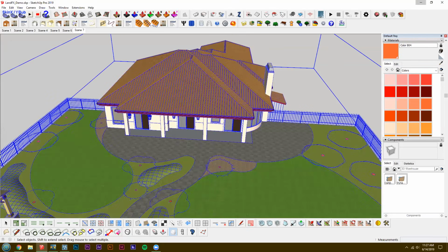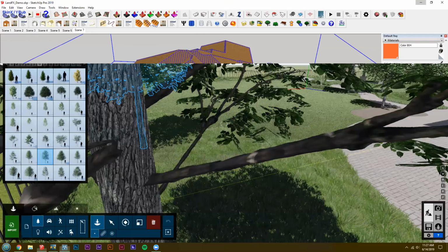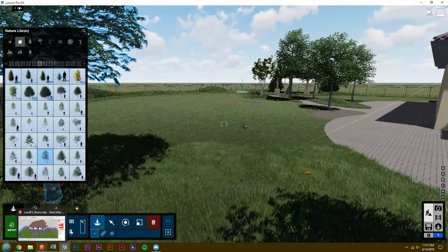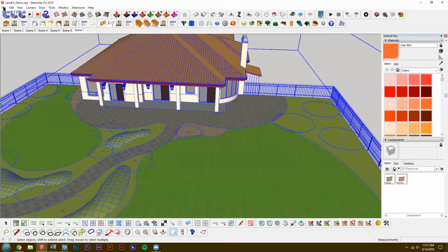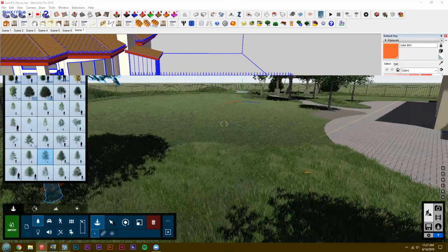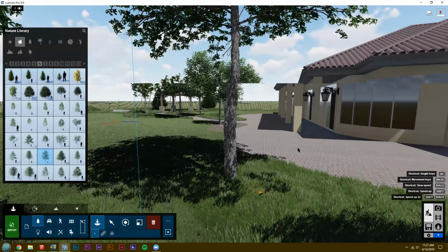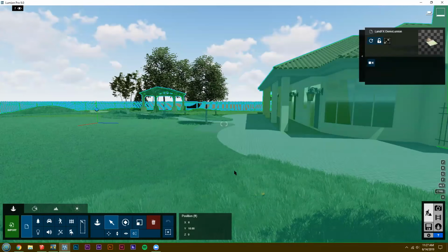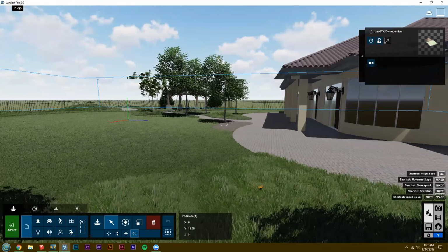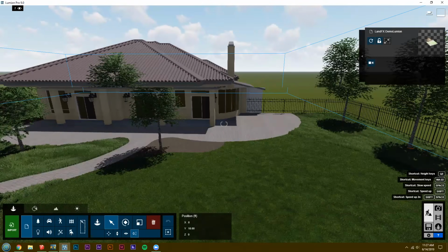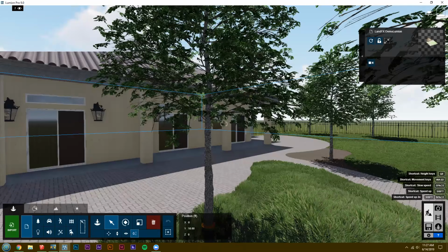So it does just move that node that it essentially started with. So you can always refresh the model, which we typically do. You just go in, resave your model, and then open Lumion again, and then just select your model, and there's this refresh button, and that'll update anything that's changed. And so that runs a bit easier than the live link. Live link can get kind of sketchy at times with big files.